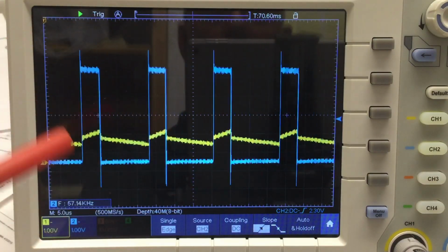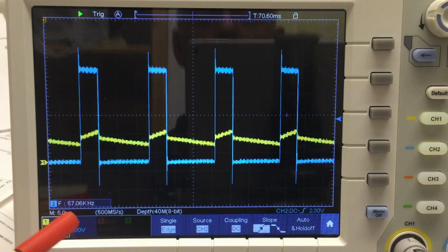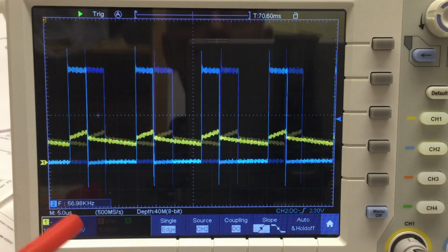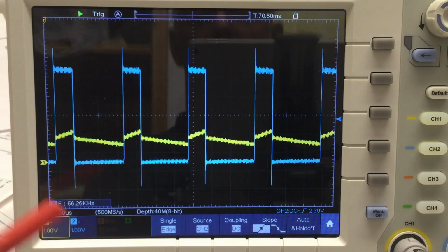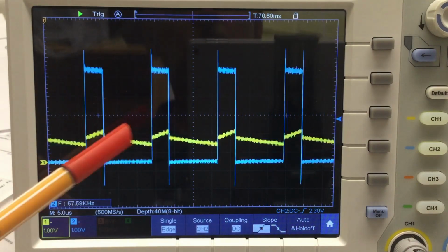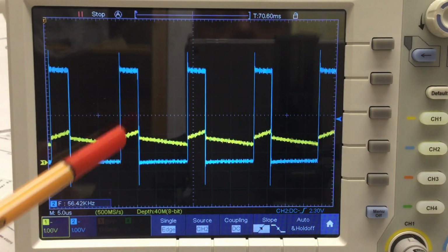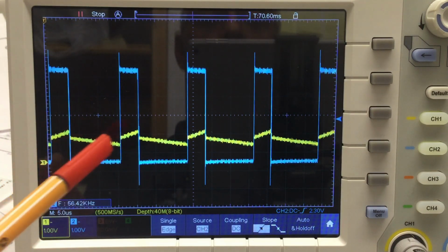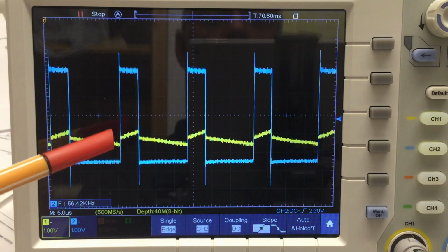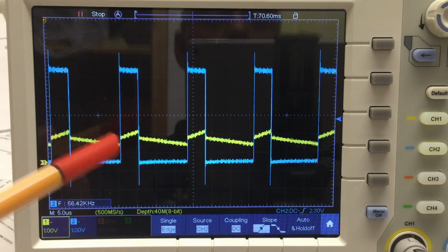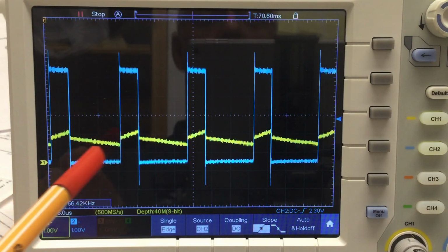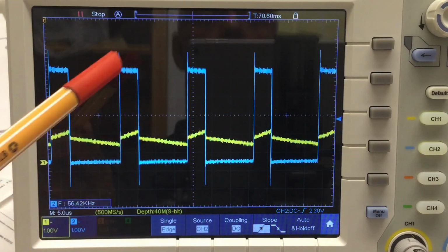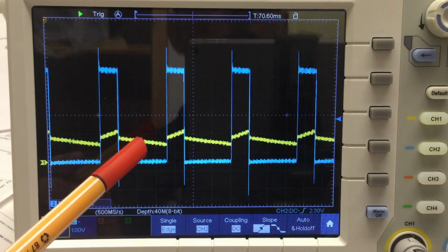As you can see, our primitive oscillator produces some jitter here, and the frequency is jumping around a little bit. But yeah, it's within a few percent, so that's okay. To be exact, about 1 kilohertz, so a little less than 2%. Let me stop the capture for a second so we can have a closer look at the waveform when the sensor is dry. So we have a discharge here and we have a charge here, and we already see there are some jumps here. Yeah, we will talk about that later. And we also see that our square wave is not symmetrical, okay? So the low is much longer than the high. But anyway, let's see if this is really working.